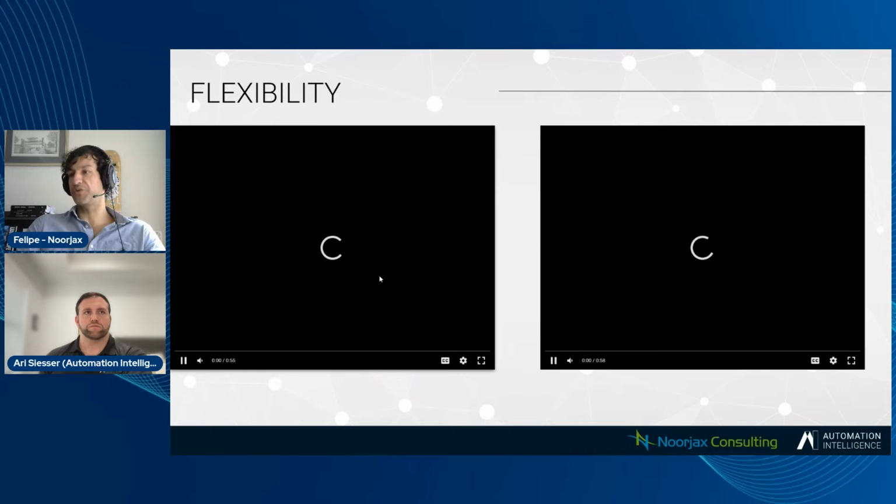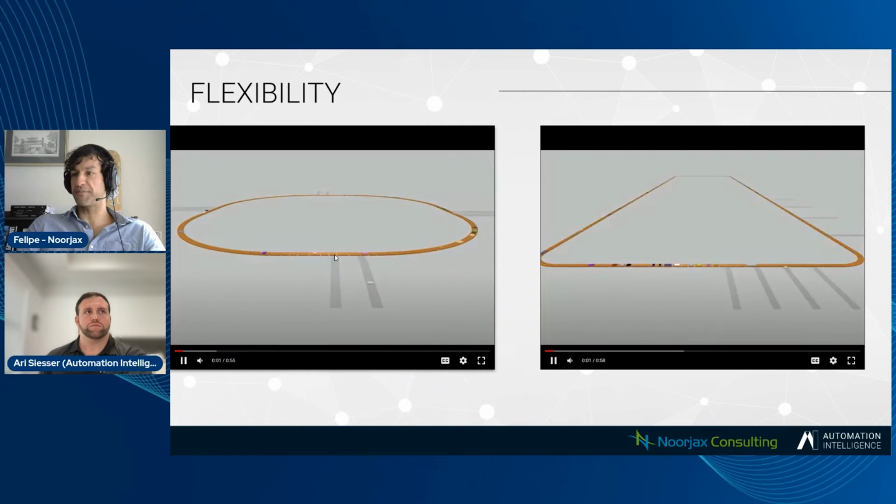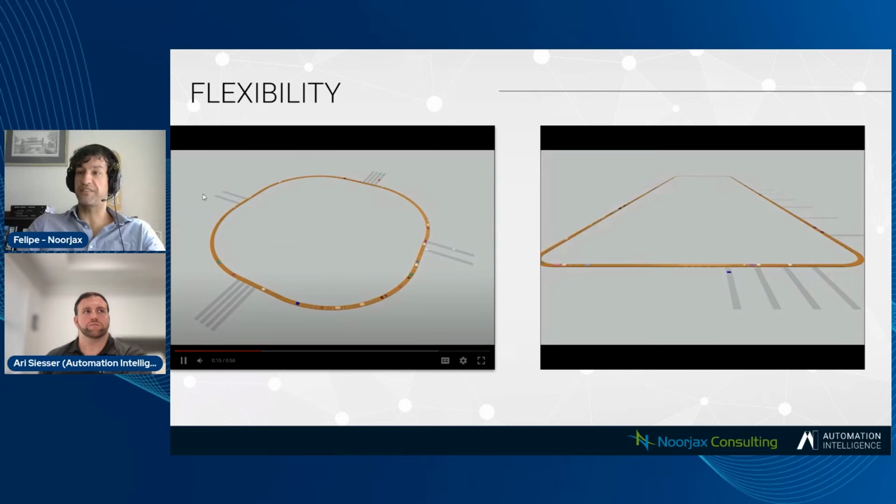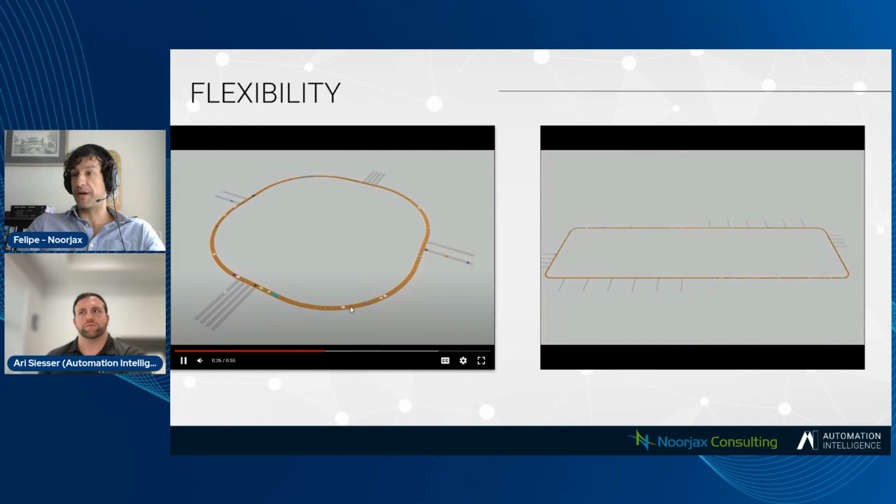So we can see two examples here. On the example on the left, this is all done programmatically, so nothing is built with any conveyor done by AnyLogic. Everything is done programmatically, so you can create two input lanes and four output lanes and a circular conveyor that is able to do the same thing, but it accommodates any layout that you have in your particular system.